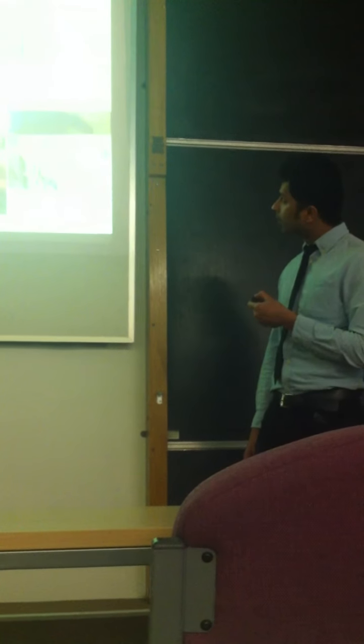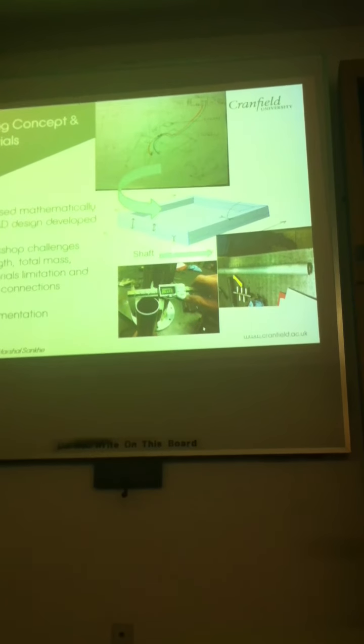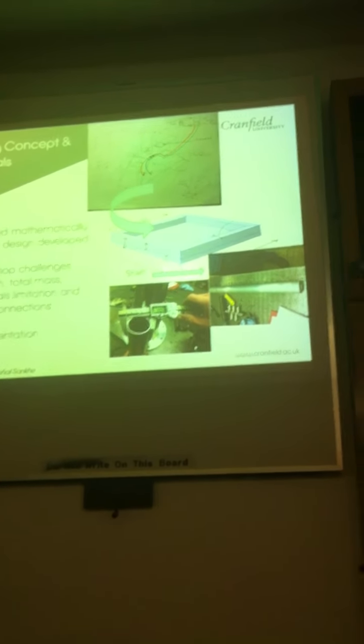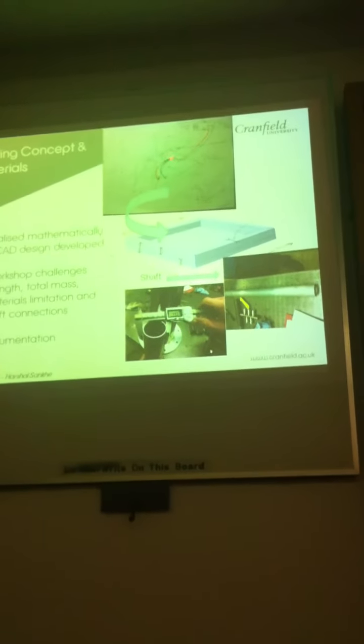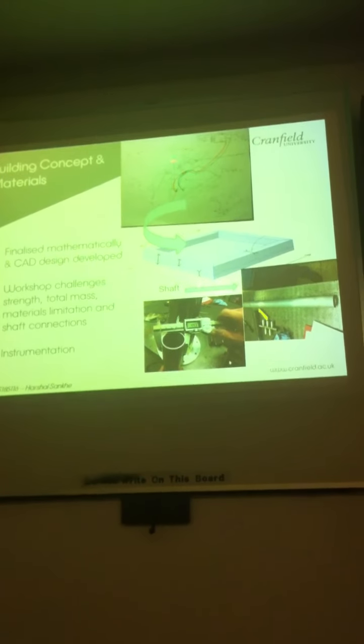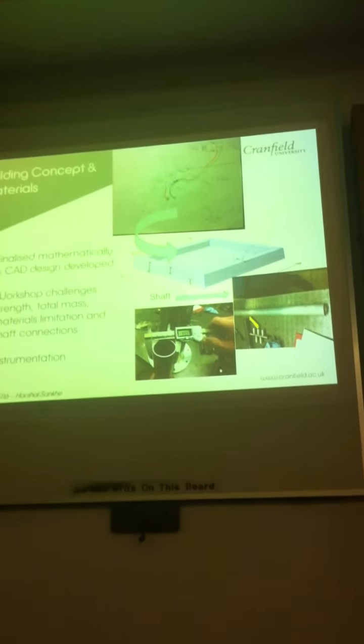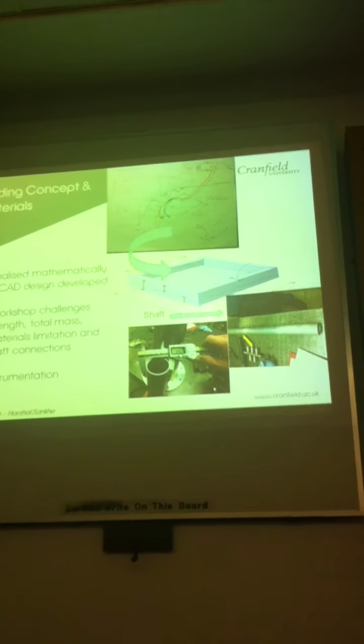So we decided on a casing of aluminium, a simple square section, and how we would put the motor inside it. The connection between the shaft and the motor was one of the most crucial, and it took us a little while to agree on it, because it leads to deflection at the top of the shaft once it starts rotating at 113 RPM.